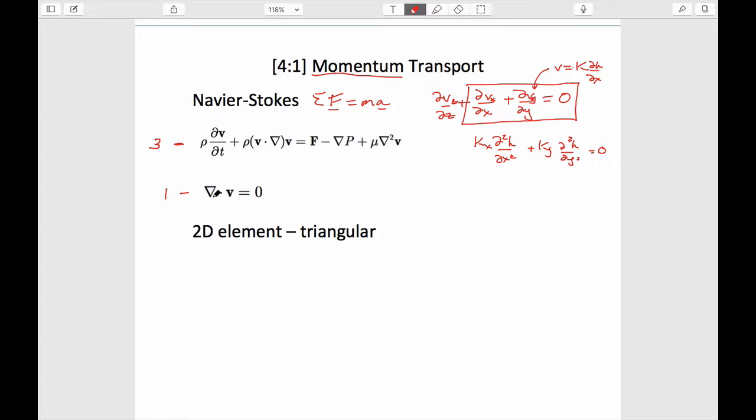If we solve things using the so-called groundwater equation, or for porous media flow in petroleum engineering using pressures, there is no conservation of momentum in that. And the assumption is that rather than momentum, this term here being important, which it isn't, what is important is the conservation of forces, and the forces are due to viscous losses. And the viscous losses come through Darcy's law.